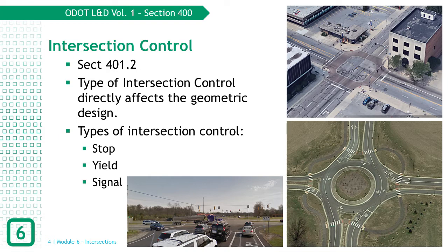Intersection Control Evaluation, or ICE, is a data-driven, performance-based framework and approach used to objectively screen alternatives and identify an optimal geometric and control solution for an intersection. The Safety Performance for Intersection Control Evaluation, or SPICE, performs an HSM-based predictive safety analysis of at-grade intersection alternatives and ramp terminal intersections and is intended for planning level safety analysis.